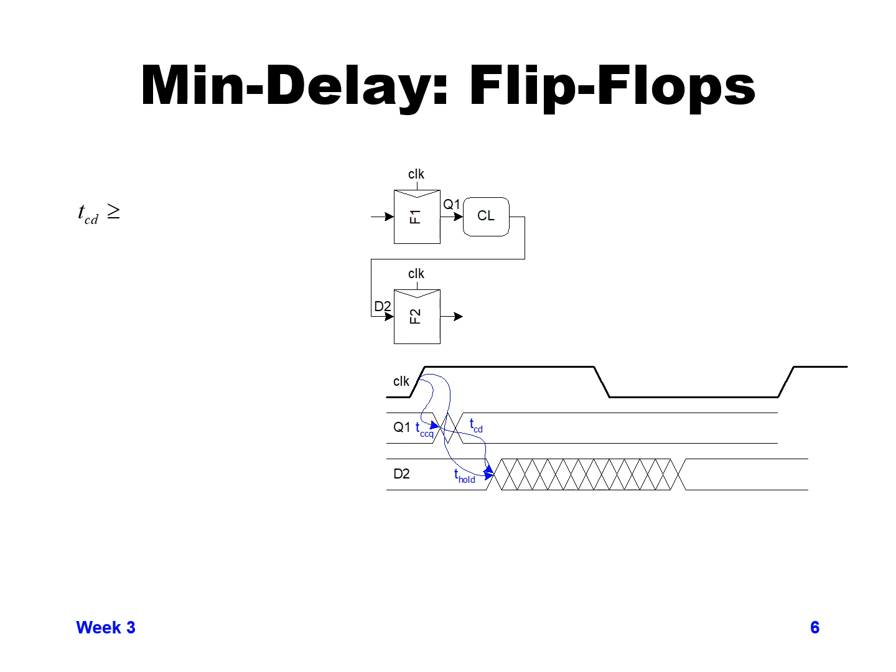And that full contamination delay of the first one through the flop and the second contamination delay through your combinational logic, that total amount of time has to be equal to or later than your hold time. And if it's not, then you could get an accidentally incorrect value going through flop 2 a cycle earlier than